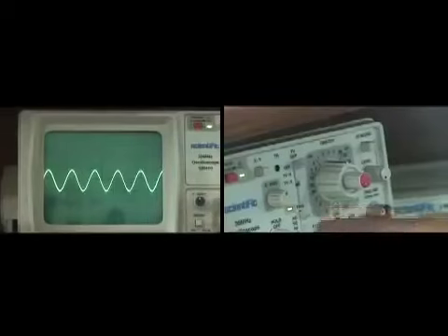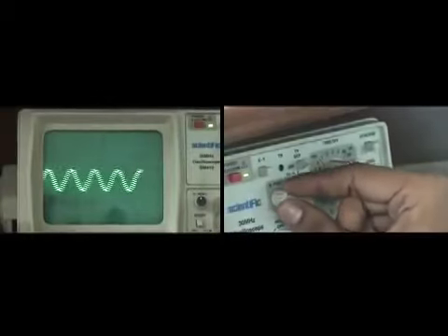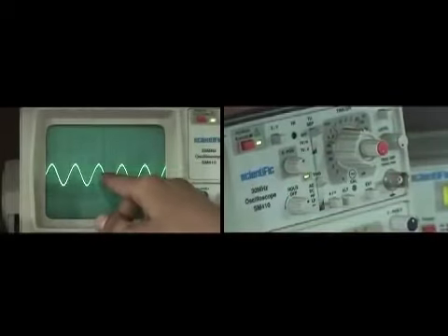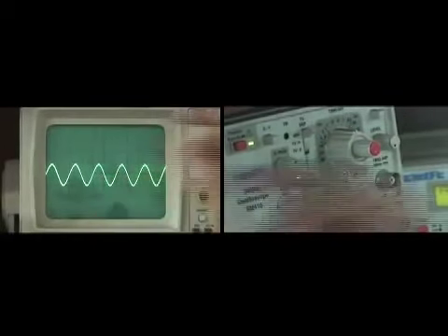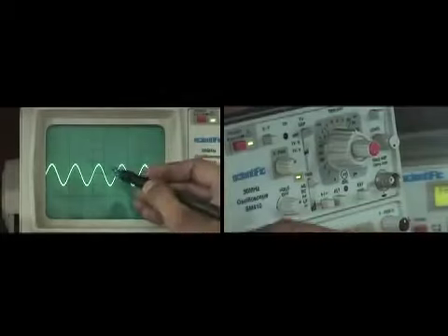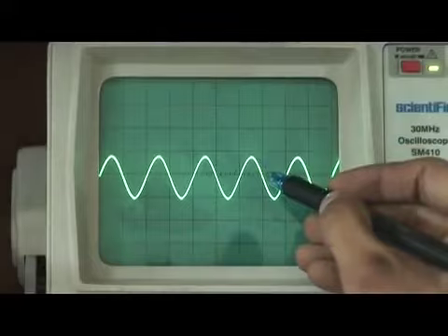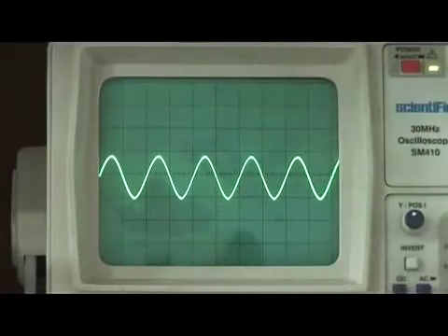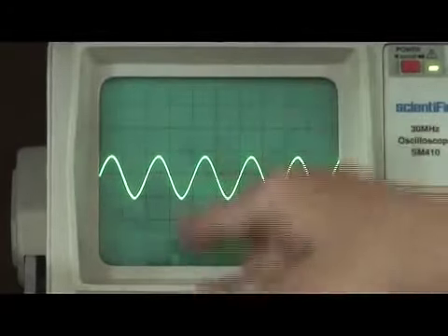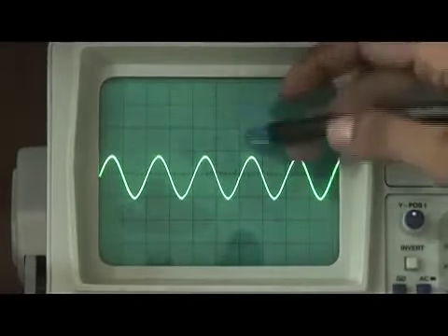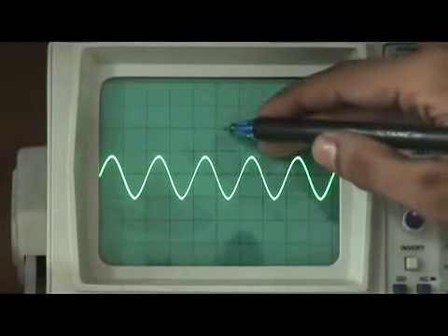So using this X position, I can move in the X direction. I am setting it in a proper place where I can take a reference point here and say that this is going to be 1. From here it is going this way, and till here it completes one cycle. So from here I can easily count the number of blocks. As I am using the term number of blocks, you might be confused what is number of blocks. You can see this entire screen is divided into small blocks, various squares. Again, you can see that each square is divided into various subdivisions.